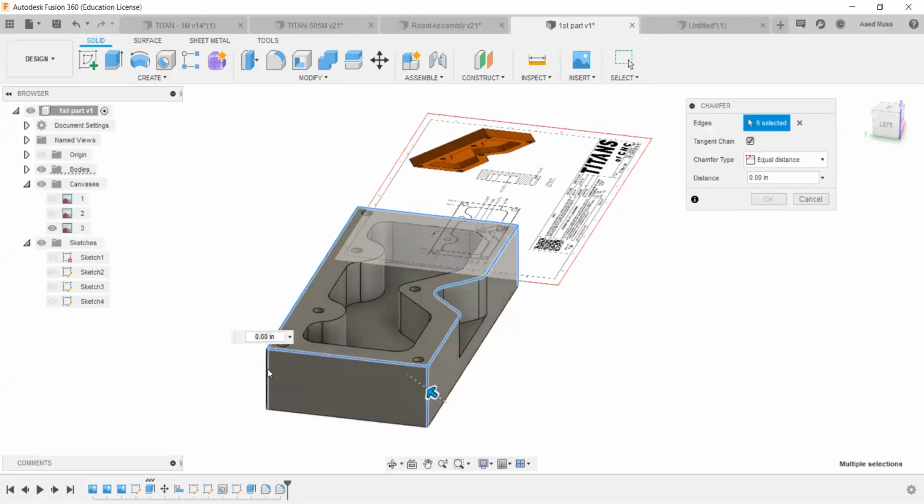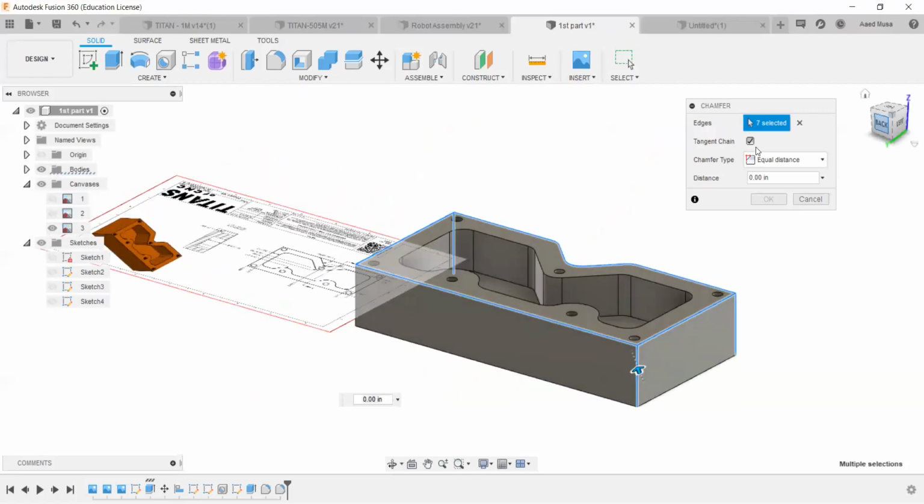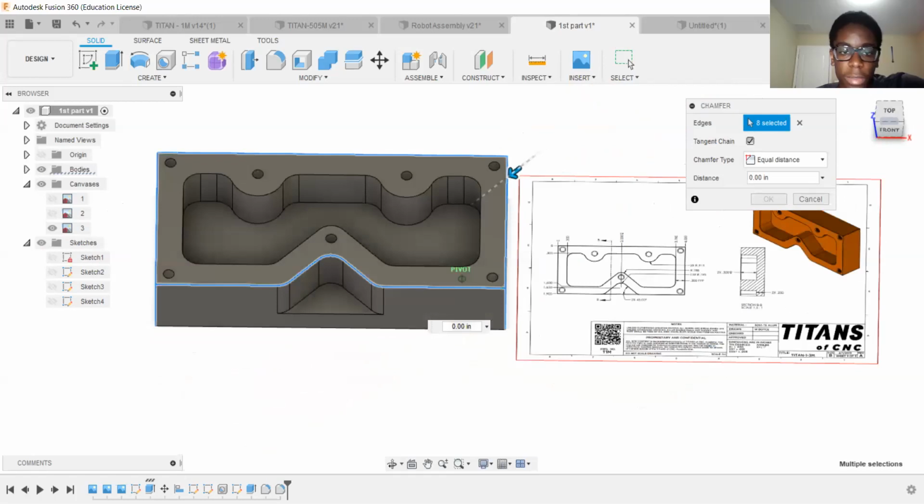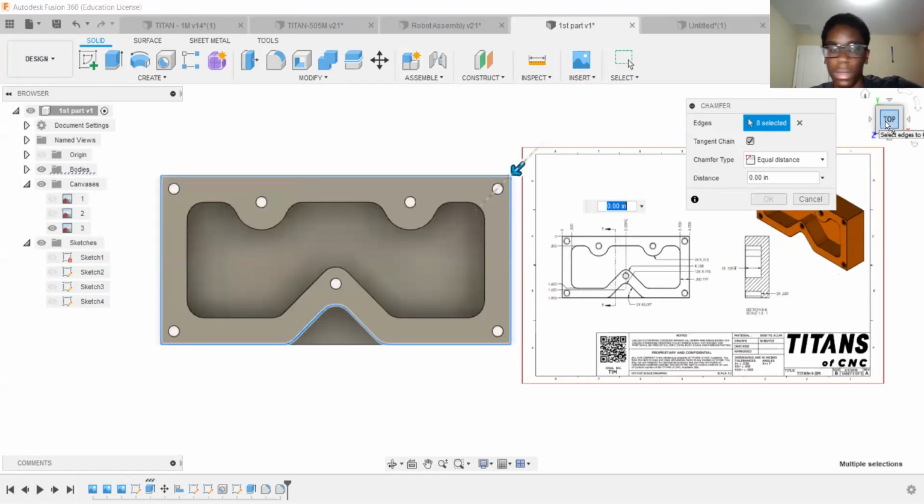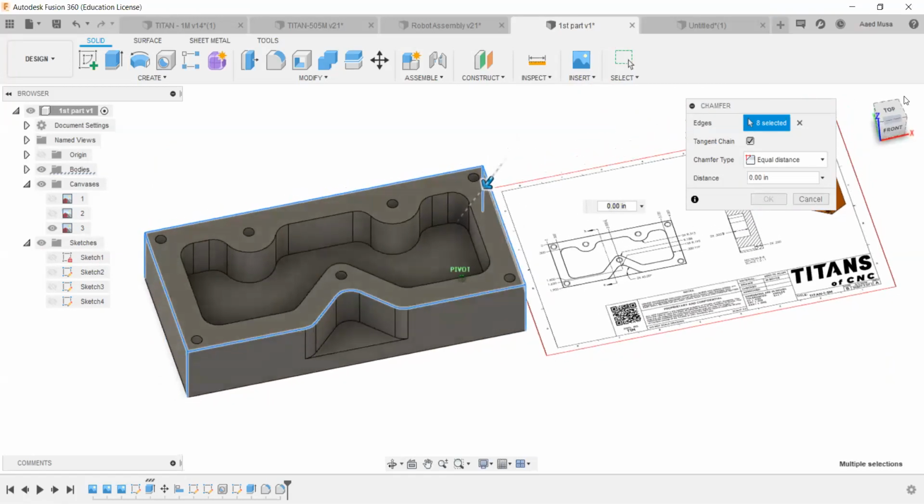And for reference, in 3D printing, you want to chamfer instead of fillet pretty much all the time. With 3D printing? Yeah, I guess so. Well, when it comes to the tops and bottoms of your model, you want to chamfer. But the curve in the center, that's fine. You can fillet that all day. That's not going to matter.